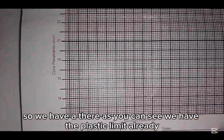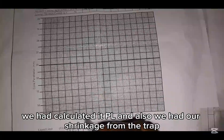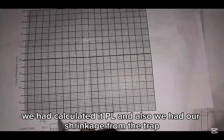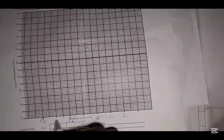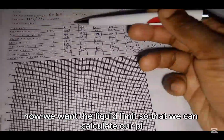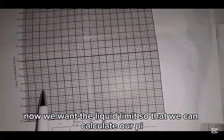So we have there, as you can see, we have the plastic limit already. We had calculated it, PL, and also we had our shrinkage from the trough. So we have those 2 points. Now we want the liquid limit so that we can calculate our PI.